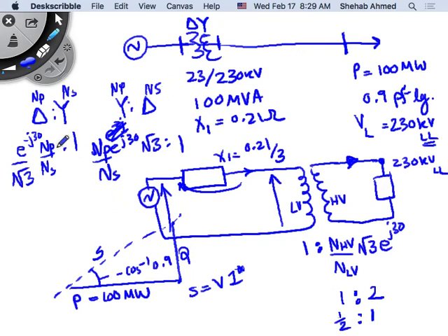So N primary is what? In this case, it's the low voltage side. Right? And here, N primary is the low voltage turns equivalent, versus N primary here is the high voltage turns equivalent, right? So that's why for me, anytime you have a delta star, on the high voltage side, put the N high voltage or N low voltage, right? You get this or not? Right? So it makes it easier.